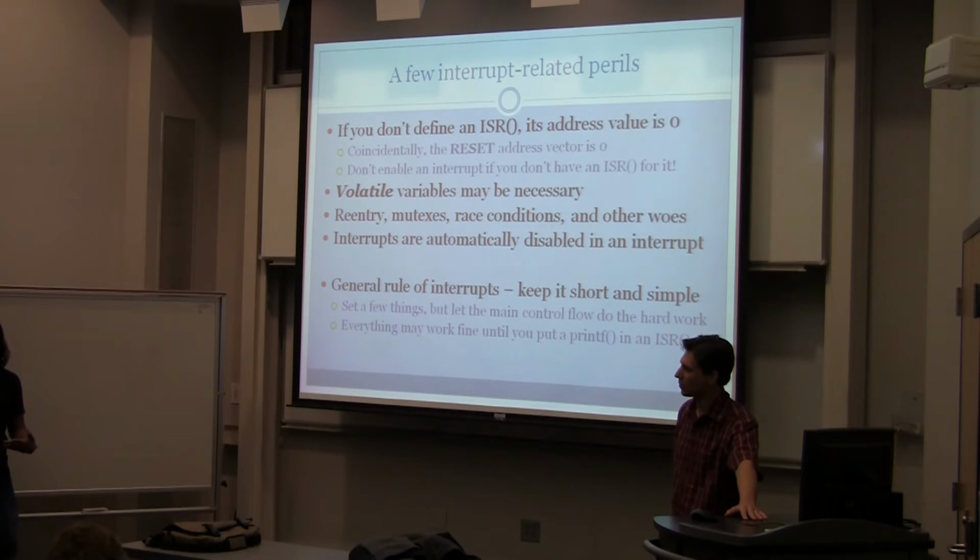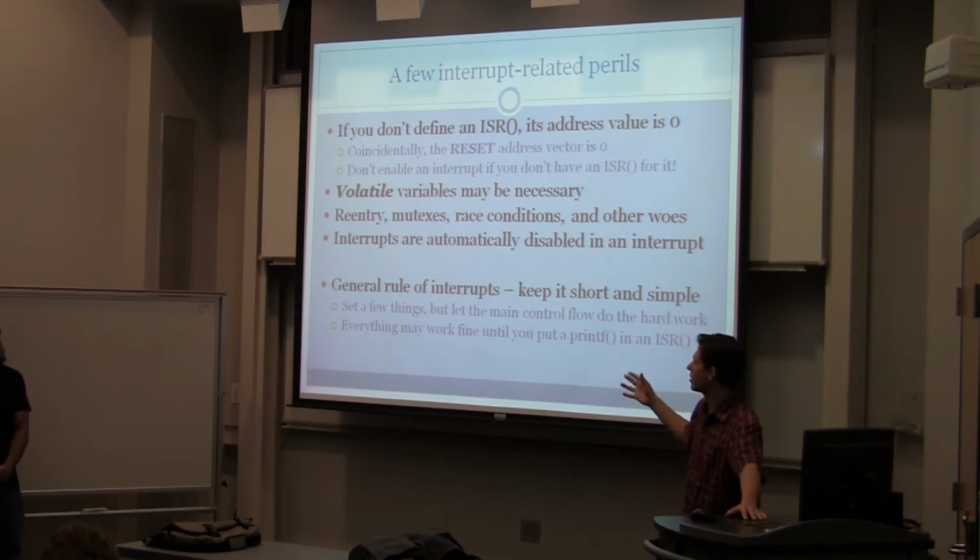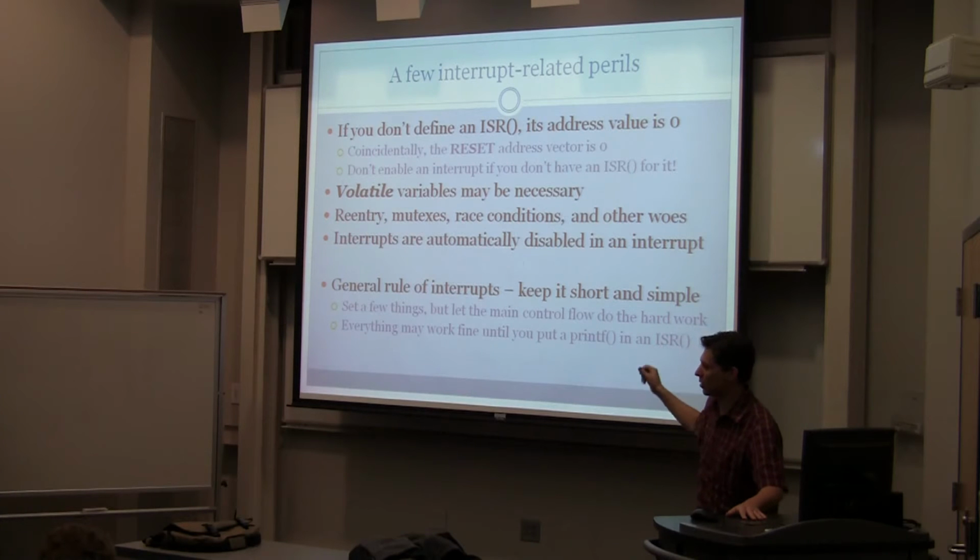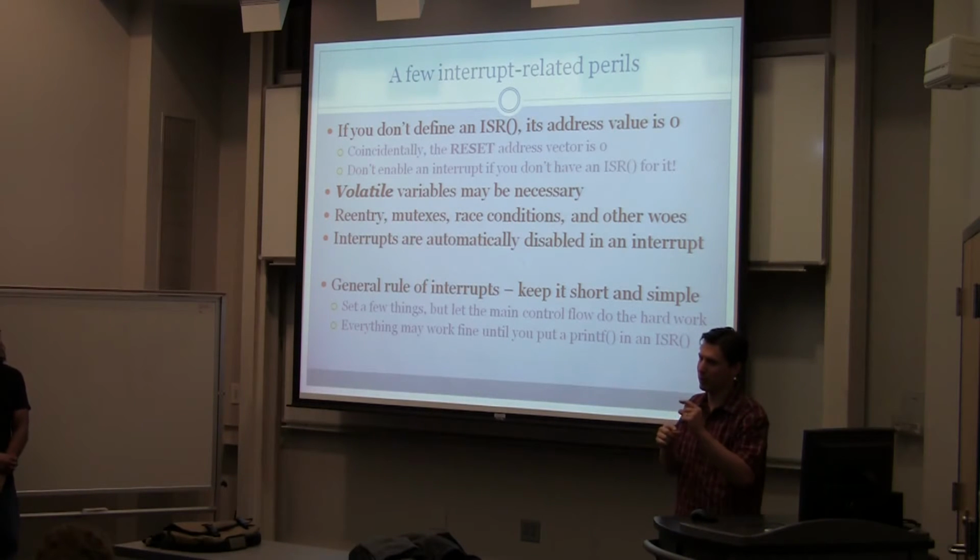So that's the sort of thing we're talking about: if these things take too long, then other stuff which was supposed to be happening at regular intervals could be delayed. The way you prevent things from getting out of sync, not happening at regular intervals if you want them to be at regular intervals, is to just make sure the interrupts are as short as possible. The code inside the interrupt, have it do as little as possible.